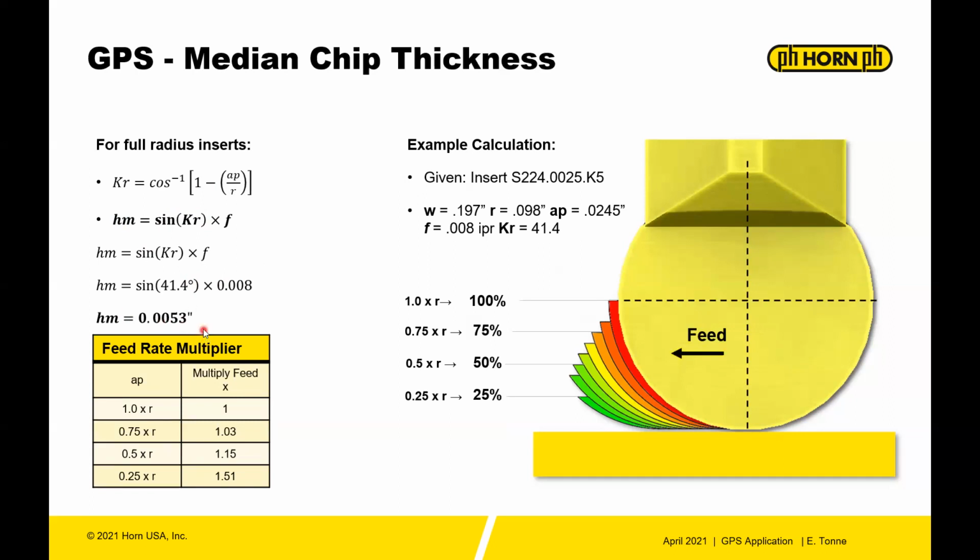So let's say for a given material and a given cutting edge, you know that your chip thickness can be 8 thousandths. You can then increase your feed to match that chip thickness. So you're managing, basically with chip thickness, the forces and the pressure on your cutting edge by how thick this chip is. So that's why it's important to know that.